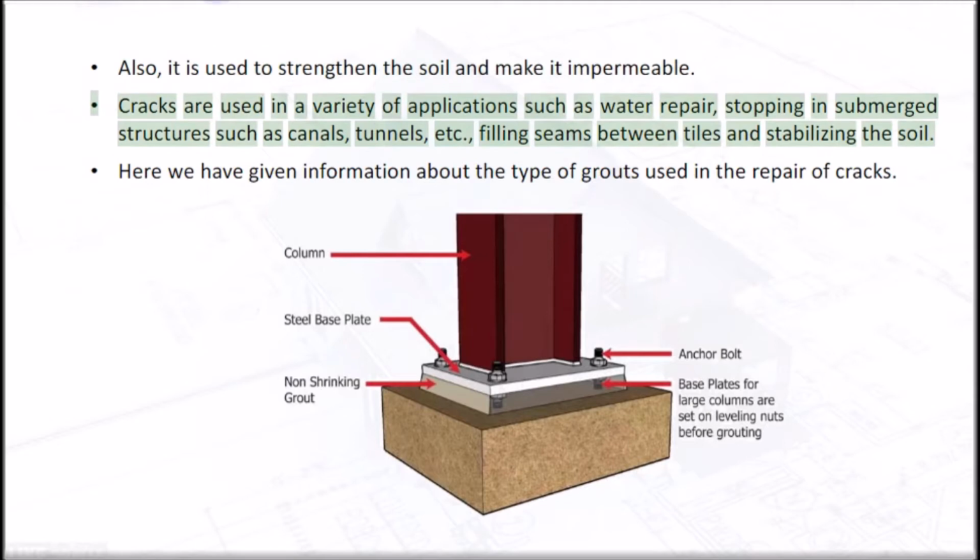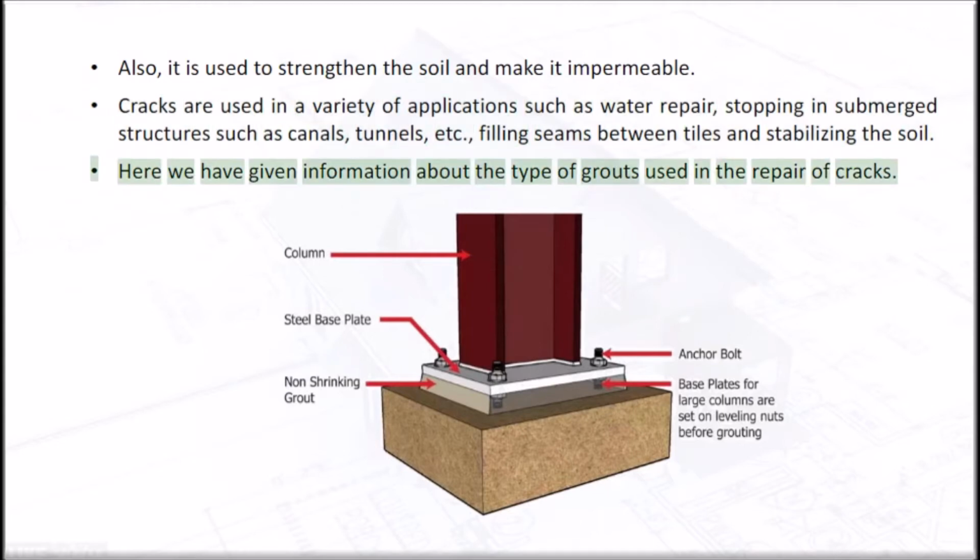Grouts are used in a variety of applications such as water repair, stopping in submerged structures such as canals, tunnels, etc., filling seams between tiles and stabilizing the soil. Here we have given information about the type of grouts used in the repair of cracks.